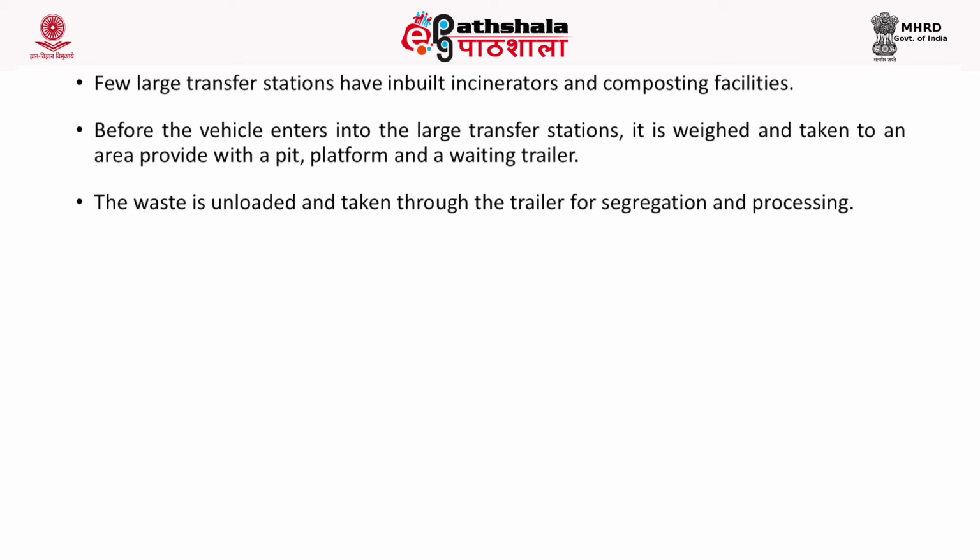Before the vehicle enters and leaves the transfer station, it will be weighed and the waste will be taken along with the truck to an area where it will have a pit, platform and a waiting trailer. The waste is unloaded and then through the trailer it is taken for segregation and processing.